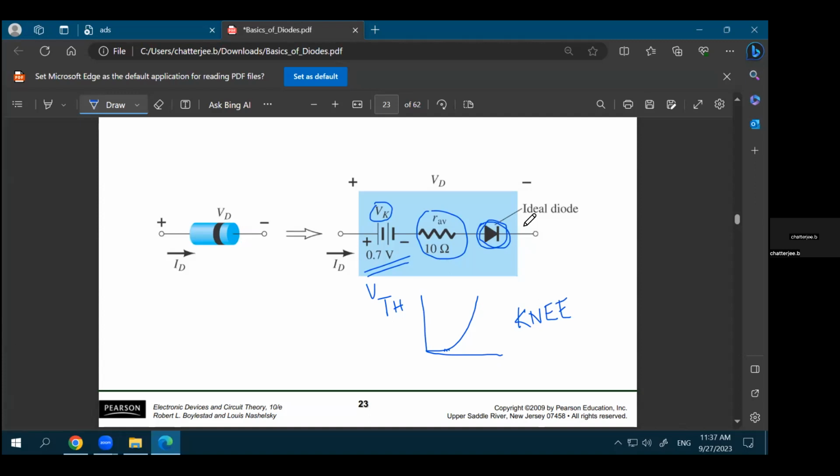This is the concept. If your offset is 2 millivolts and your gain is 1000, because of that offset your DC point will be shifted by 2 millivolts times the gain. Oh, okay, that makes sense. Thank you.